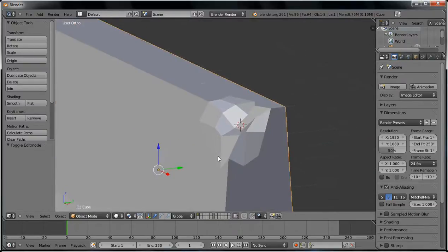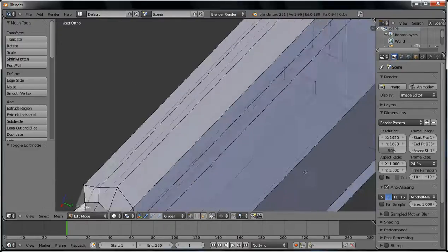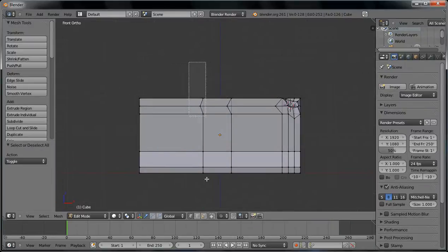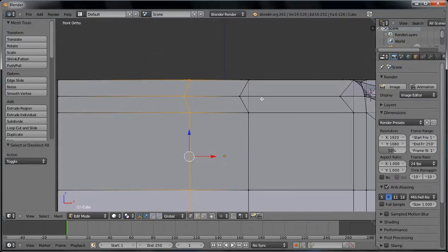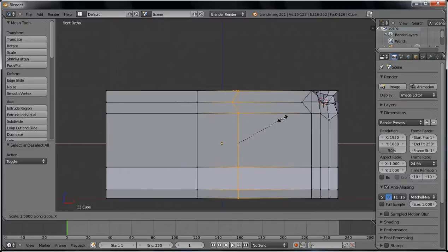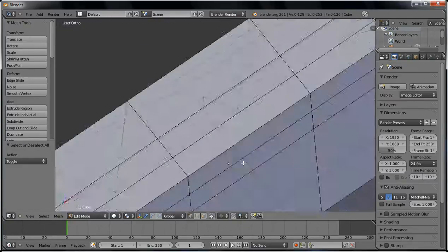That'll work for now. And then in the middle, let's have an edge ripped off on the side right here. So we'll just add 2 edge loops. We don't want these jagged, so we'll scale along the axis to 0. Do this edge loop, scale x 0, and now they're all flat and good looking.